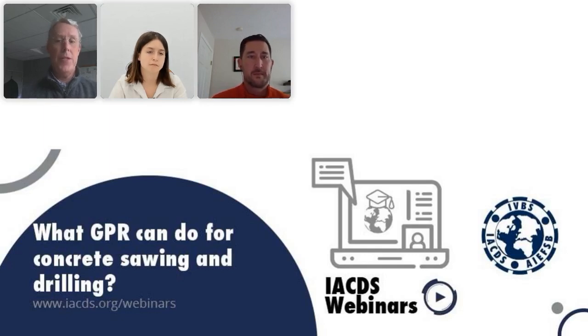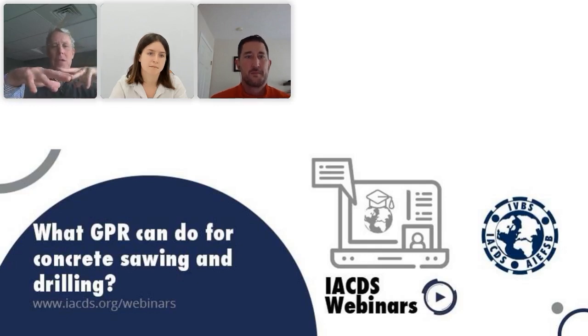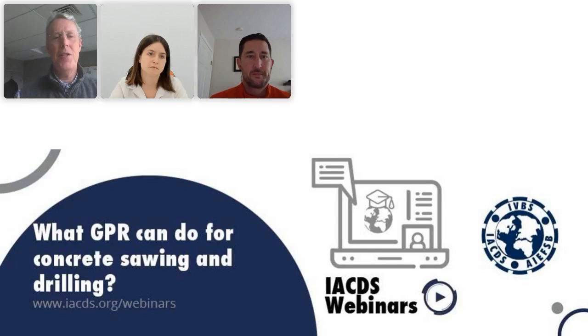So the answer to the question is yes, PT cable can be hidden under rebar. That's why you must have a larger picture to figure out where these things are. Because if you do one scan, you have one target and a target underneath it. It may be a multiple reflection of the target above it. It may actually be hiding the PT cable that's right underneath, but it can't hide for long. The PT cables move, change depth, and undulate, whereas the bar doesn't. So you can usually figure it out.